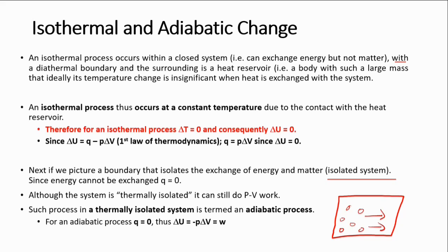If they are expanding, then that is work, because there's an increase in the volume, and the pressure is constant. However, there can be no exchange of heat with the surroundings. That is not allowed for an adiabatic system. There's no exchange of heat.